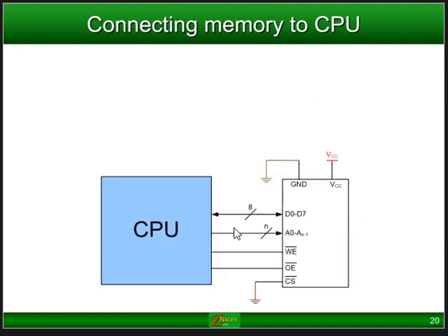And then you will connect your CPU to this memory device. Depending on the microcontroller or microprocessor that you use, like the 8051, you will have memories outside. You will also have memories inside, depending on what 8051 series you use. But in the case of the AVR, the ATmega for instance, your memory device and your CPU will be one complete unit. Everything will be inside. In other cases, you can have this memory device externally and then connected to the CPU, depending on what microcontroller or microprocessor you're making use of.